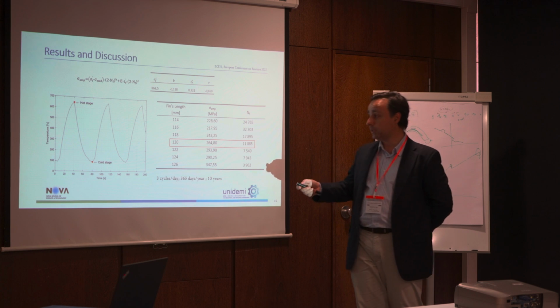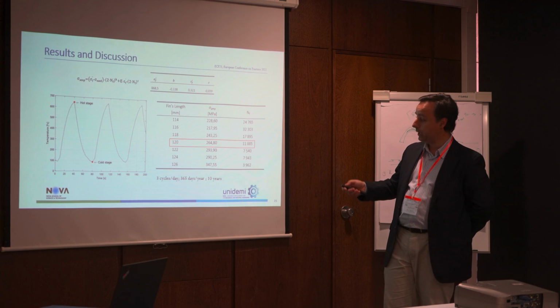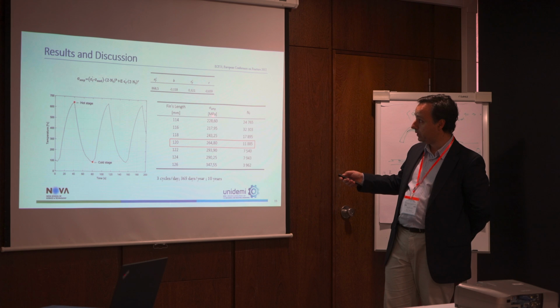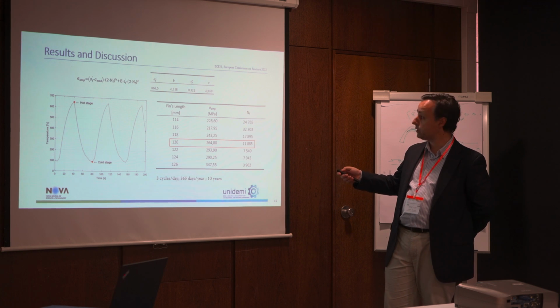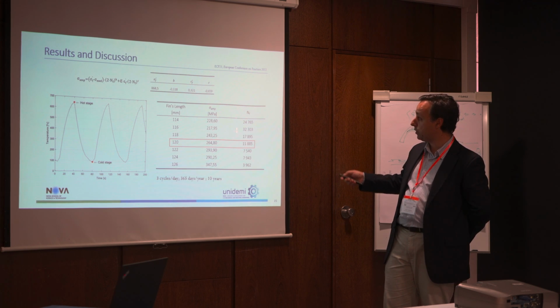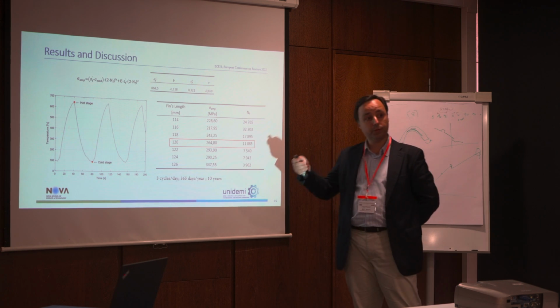Considering a cycle defined by the hot stage and the cold stage, and using the Coffin-Manson equations and the parameters for the Coffin-Manson equations, we have determined for the different fins with the different lengths the amplitude stresses and the mean stresses, and we have determined the number of cycles until failure that are estimated for each configuration.